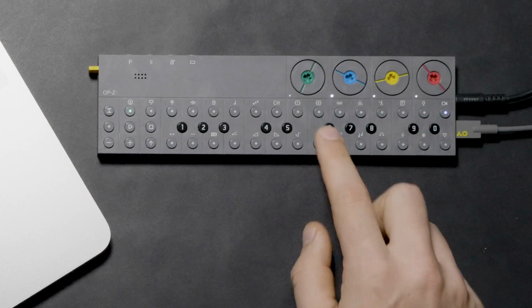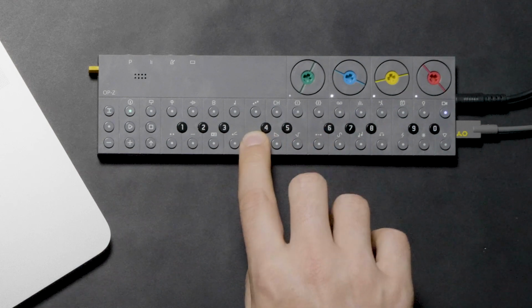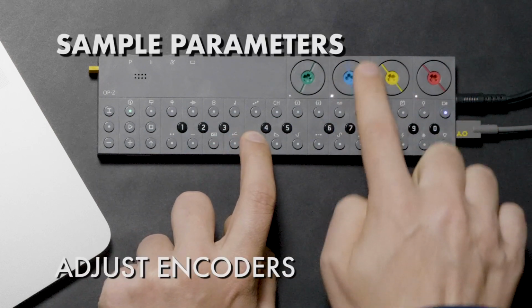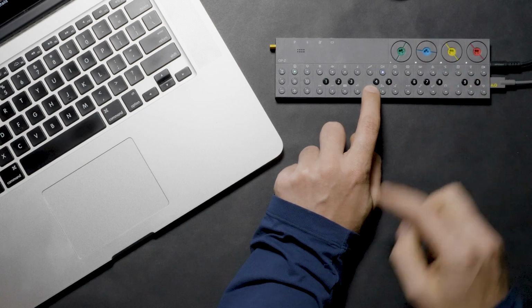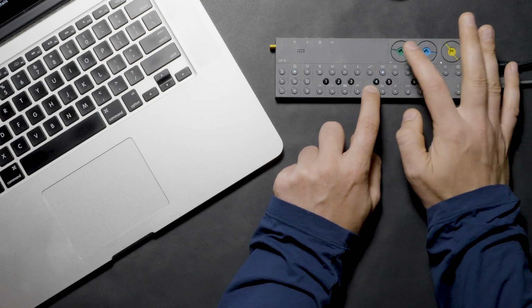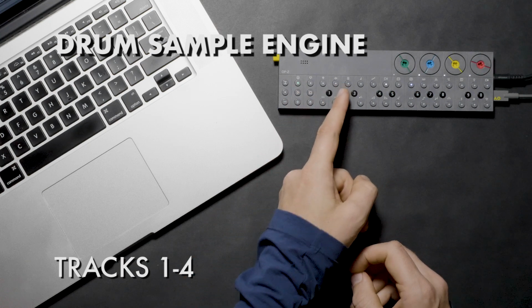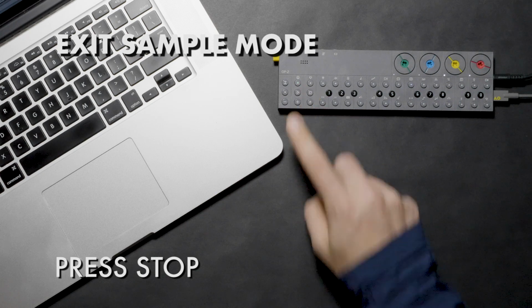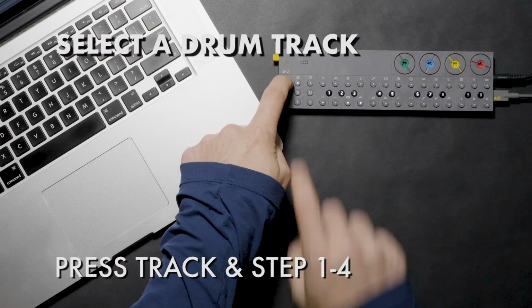The OPZ can't sample. At this point, we can circle back around to the other sample engine on board the OPZ, which is the drum sample engine. Remember, the drum sample engine is only on tracks 1 through 4, so we need to switch to one of those tracks. Press stop to make sure you're back in sequencer mode. Press and hold track and then select a track between 1 and 4.